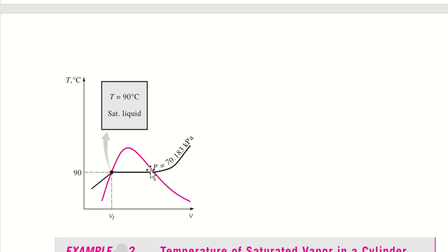And once you keep the temperature sustained for some time, the water is going to vaporize till it hits the saturated vapor line and the superheated vapor along that pressure. Yeah, that's the specific interpretation. And why was it a Tv diagram? Because we're doing everything at a constant pressure. So you know that whatever is changing is the temperature and the specific volume. And this is not total volume. This is small v, which is specific volume.